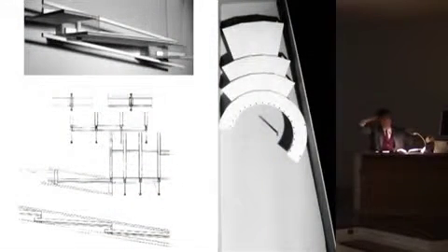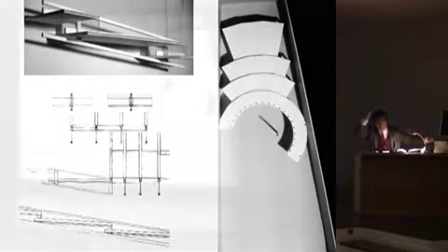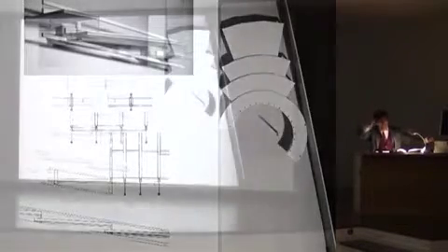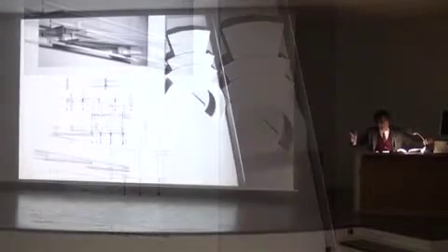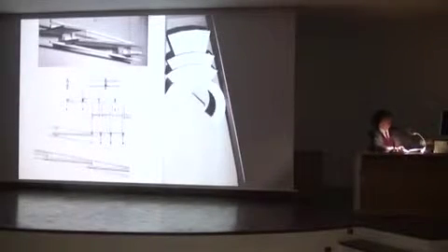I can rest on the wings of the omega the plates of the roof toward one side and another, and they rotate in a polygonal way. And secondly, they don't get together, and they're the drains. They project to the outside, and then water coming from the roof goes through the omega, and it becomes like a gutter. And this omega piece here is size 40, 4 centimeters.